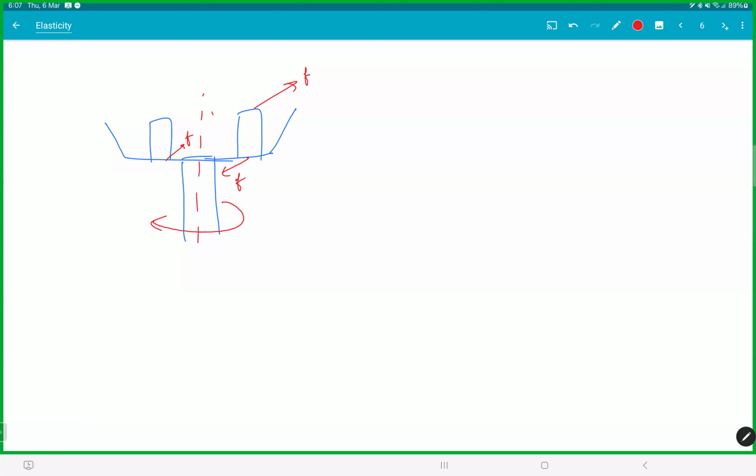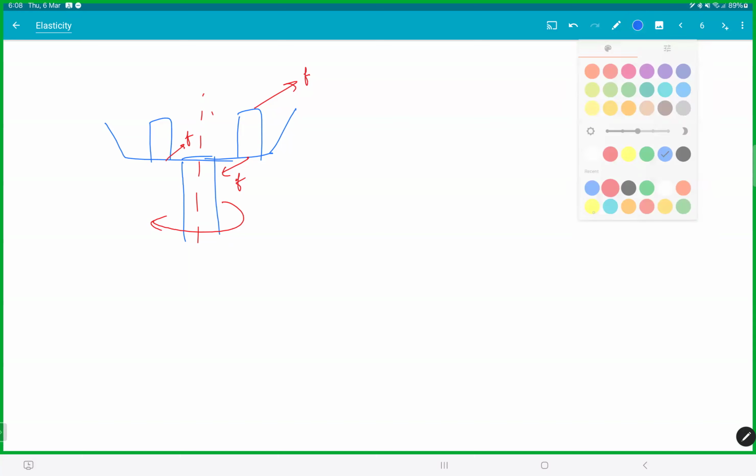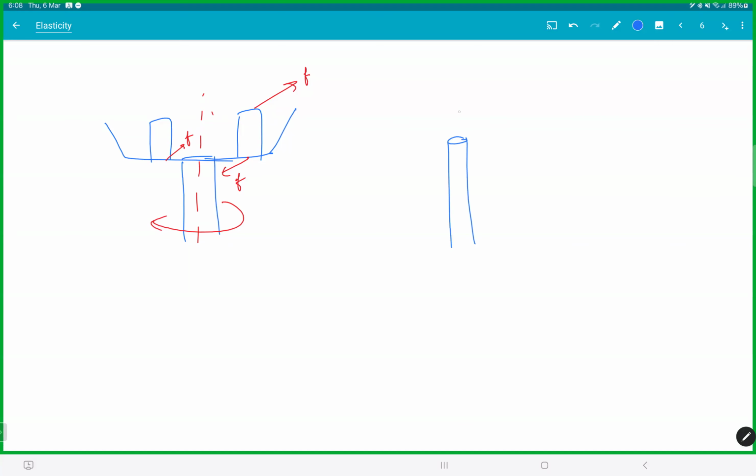Every time the train goes over that section, the pillars are getting twisted, isn't it? But if you're building a monorail, you can avoid this. You know why? When you're building a monorail, you will keep the train exactly on top of the pillar, isn't it? Even then, you'll have a slight problem. You're actually twisting the pillar front and back. But generally, these elevated structures have very thick pillars.